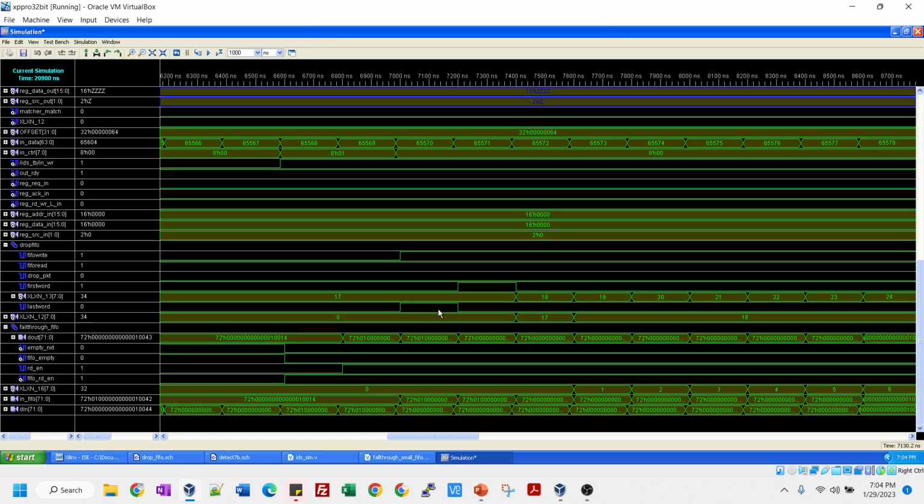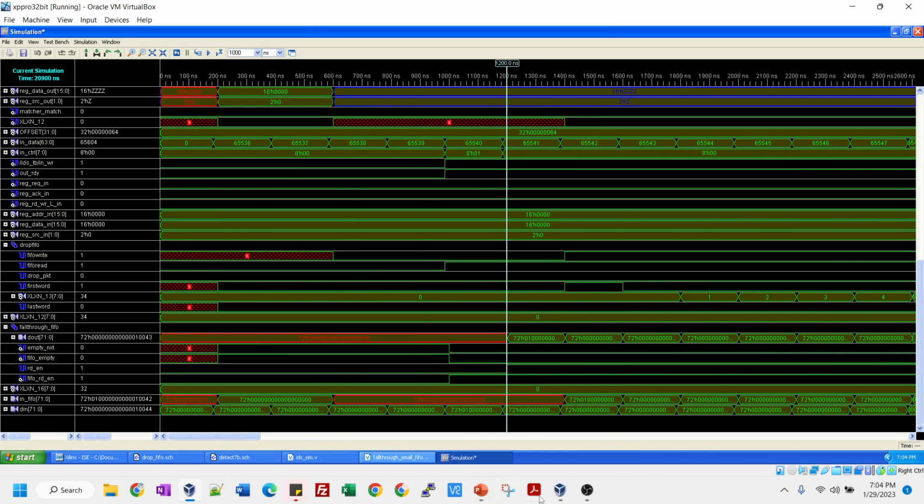the last word signal is high, and here my WP history is 0. At the end of the packet, given there's no match signal and no detection of a malicious pattern, my write pointer history goes to 17. So proceeding to 17 gets the old value of my WP counter. So this is how my system is working.